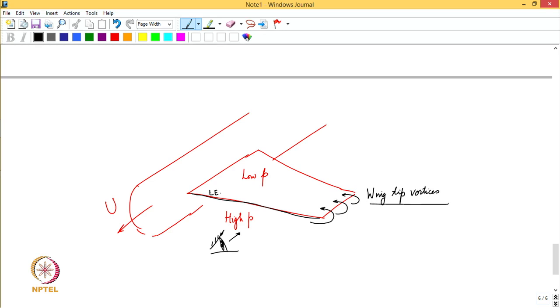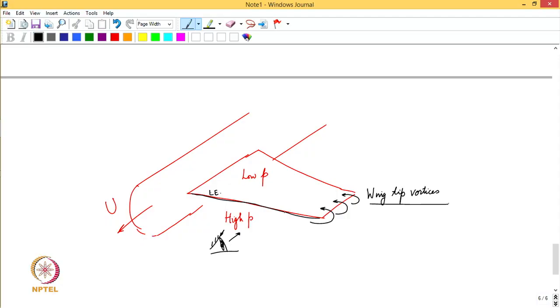To model this kind of behavior near a solid object, in which case we are assuming that the solid is a thin structure, we can use this idea that the complex potential to describe this type of flow would be proportional to square root of z, and that would give us the flow around this sharp edge. So, when you see from this distance you will not see the depth, but you would definitely see over the wing this kind of flow pattern, which is what we have now been able to